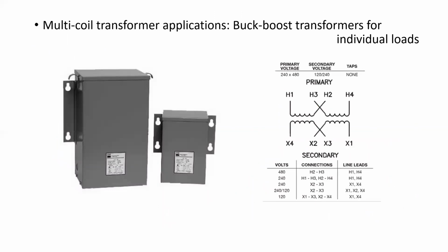So where are we going to use these multi-coil transformer applications? Well, there's obviously buck-boost transformers, which is what we've done a few calculations with. There's actually more combinations than what we just looked at, those four, and that would require us connecting them in auto formation. We'll look at those in an upcoming presentation.